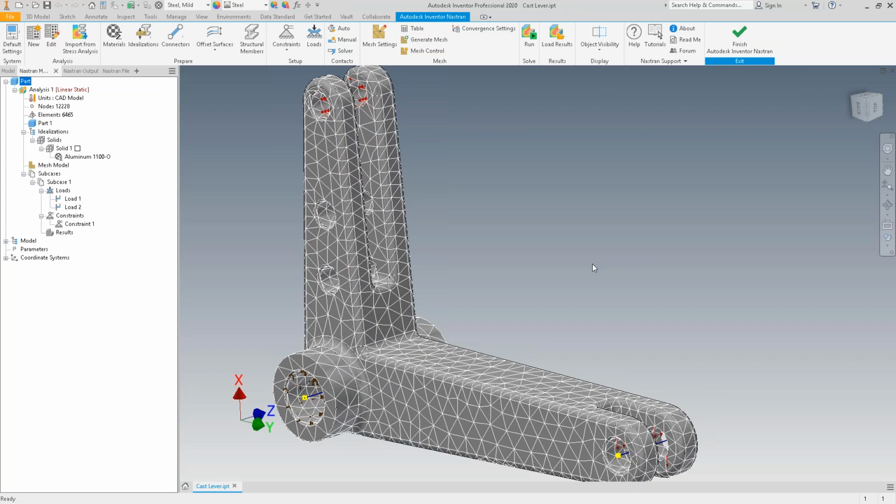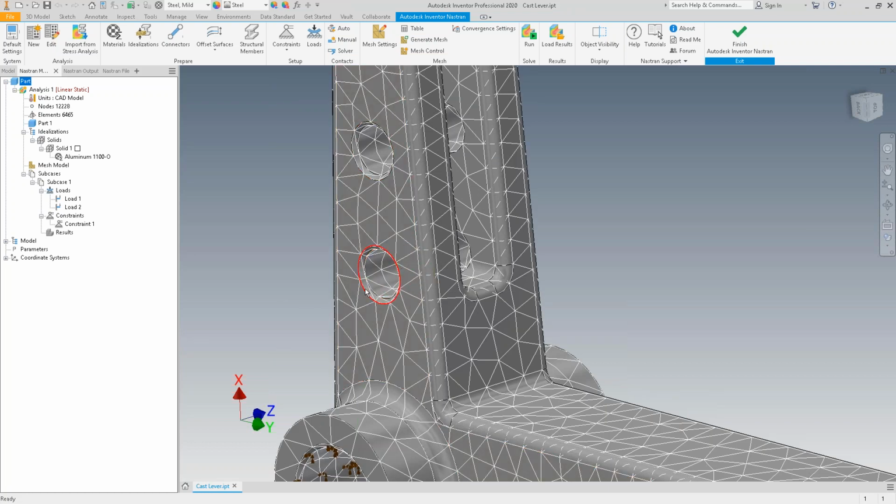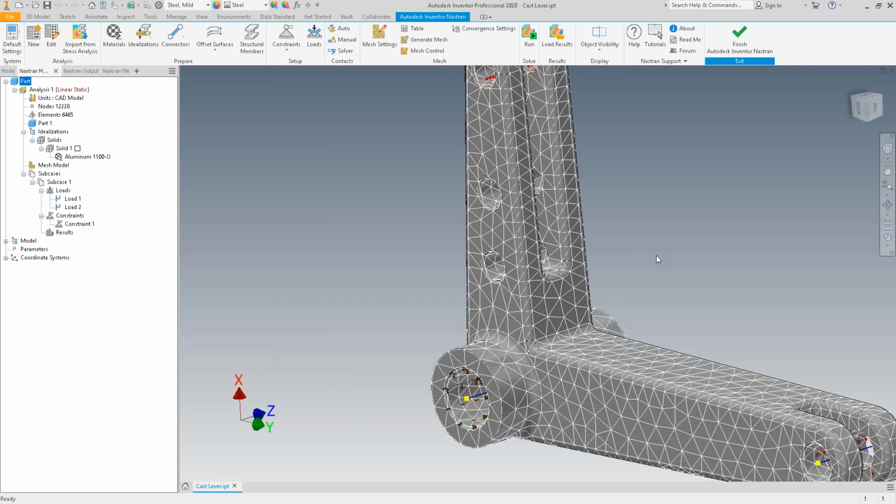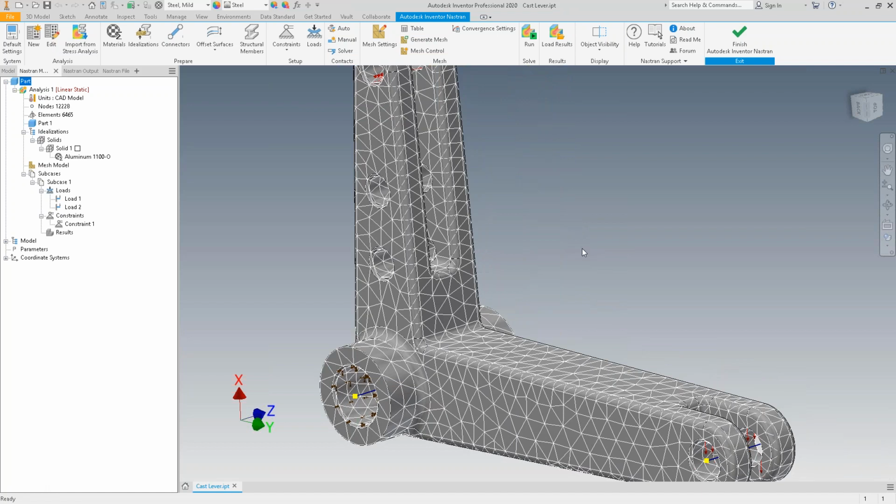That's important, because when you're looking at the mesh of a model, you want to make sure, one, that the distribution is nice and uniform. You don't get any crazy sudden changes in your mesh pattern for no obvious reason. You start going around drilled holes, the mesh pattern is going to change orientation. It may even change size a little bit. You go into a smaller face, such as the chamfered faces of the drilled holes, it's going to change size, it's going to change orientation.